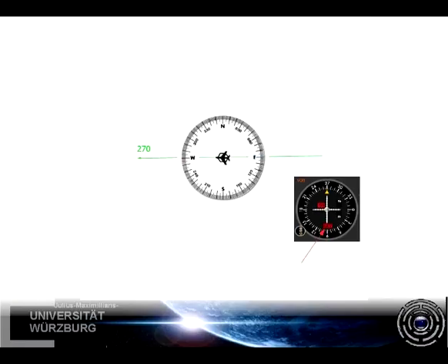As we approach the station, we enter the cone of silence, the part where no reliable reception is possible. As soon as this is the case, the nav flag shows on the instrument, showing that no interpretable signal is present. When we have reception, the indicator shows our deviation from the desired path again, which in our case is still 0. The difference to the previous indication is the from arrow that is now showing as opposed to the to arrow that was illuminated before we crossed the VOR.